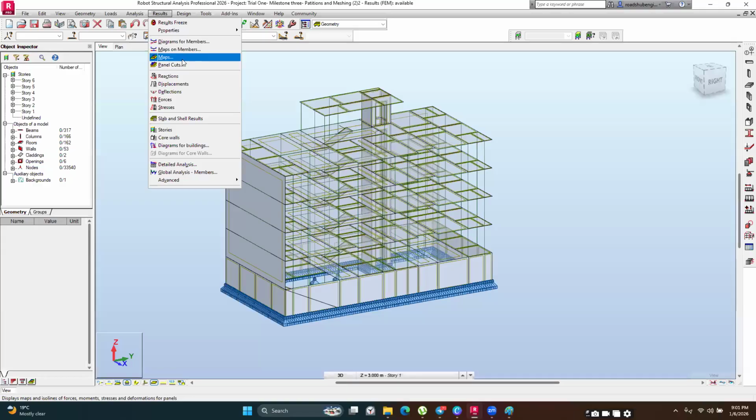So for maps, you're going to be looking at the bending moments for the slabs. So when you look at the bending moments for your slabs and the deflections, you expect the maximum bending moments will probably be near the midspans of the slabs. And then for your hogging moments, you'd expect them to appear near where you have your supports. Okay. And then for the displacements, this is just a table to enable you to see, say, the maximum displacement of your structure. And then from there, you can be able to see if it is viable for construction. Okay, so let's get started.